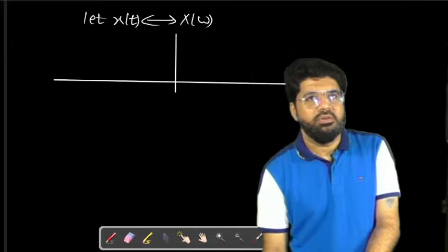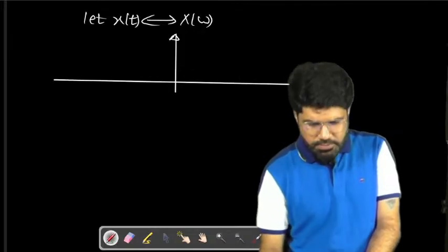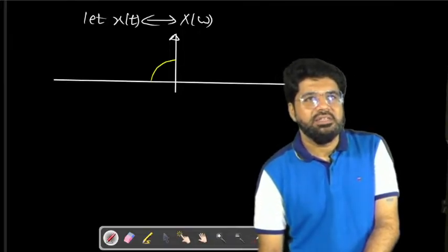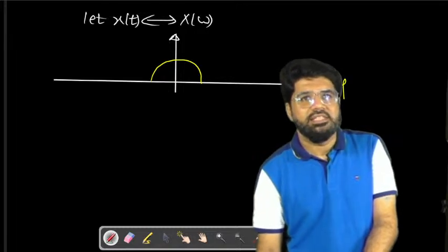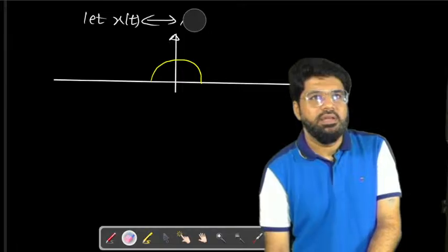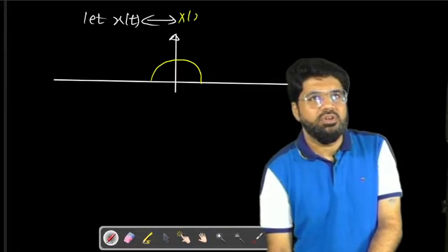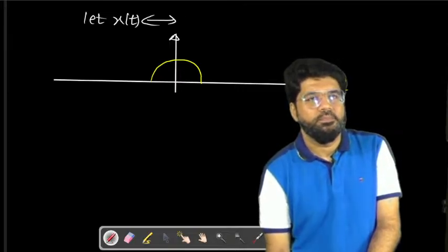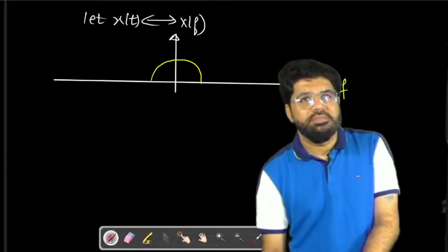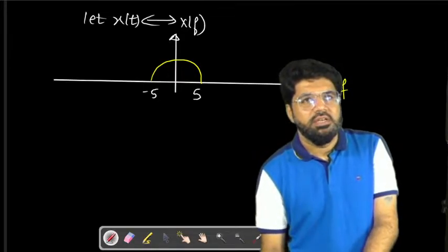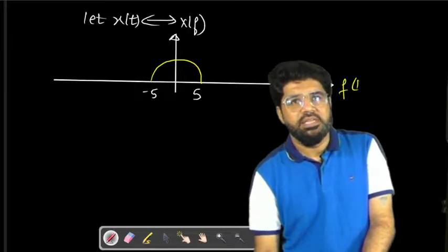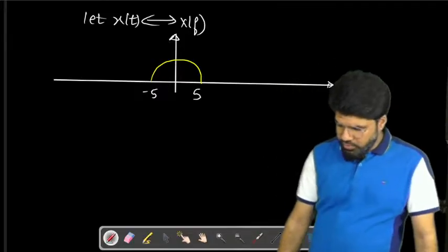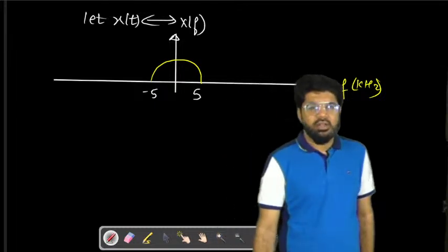Step by step explaining it to you. So the Fourier transform sketch of X omega, consider anything like this, and taking it on f scale. Let's say this is f, and let's take it in the f domain only. Suppose this is X of f. So it is band limited up to 5 kilohertz, 5 and minus 5, assuming that this frequency is in kilohertz. Okay, band limited low pass, it is only up to the low frequency of 5 kilohertz, correct? This is the Fourier transform of x(t).